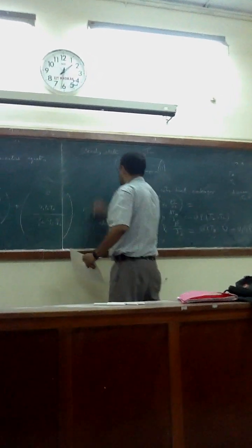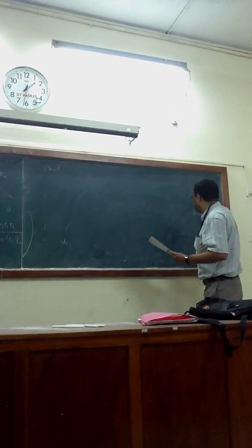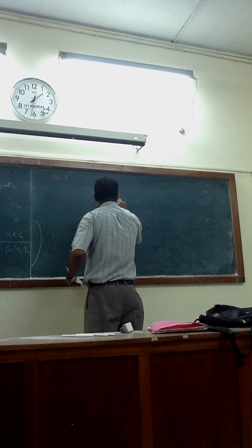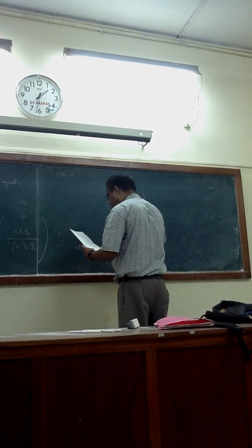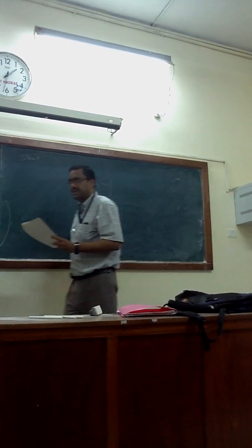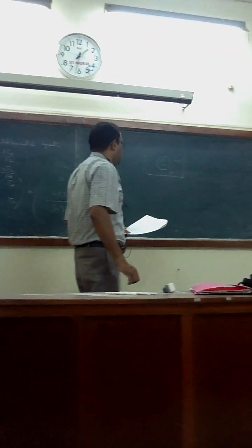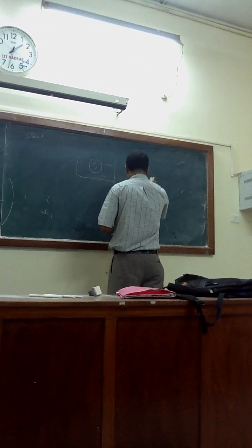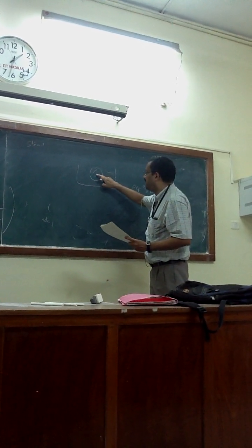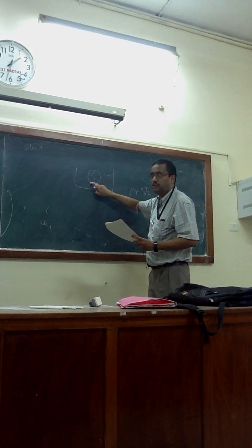That's the question. So, let's look at the spherical pellet problem, dipped in a bath. What actually happens? This guy will be losing temperature, and it is a time dependent problem, right? So the balance equation should have time dependency, which is rho Cp dT by dt. And what actually happens? There is a space gradient. Here the temperature is high, here the temperature is low, because it is directly contacting cold water.